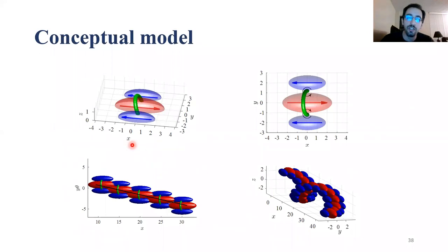Are these eddy structures actually common around the center line of the jet, or more common around the shear layer? My first answer is that these are more common around the shear layer and less common around the jet center line, but still within the turbulent region, not outside the turbulent flow. So you're mentioning the shear layer where the time average Gaussian profile has the maximum slope. Yes, exactly. Thank you.